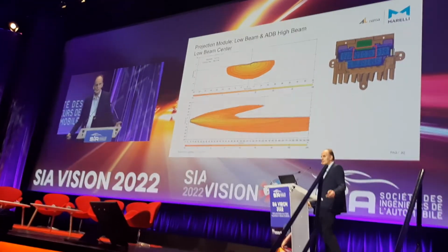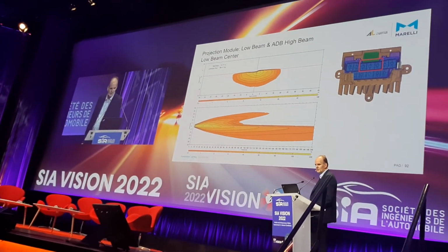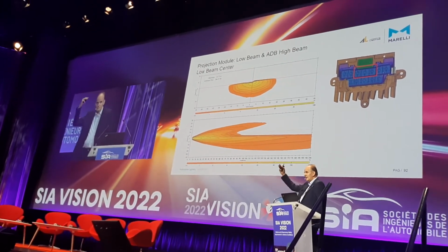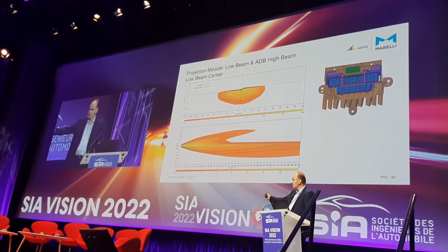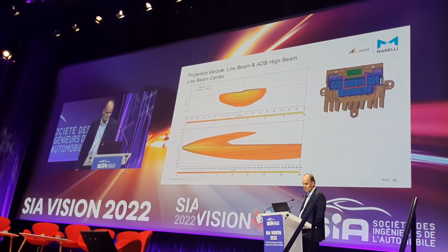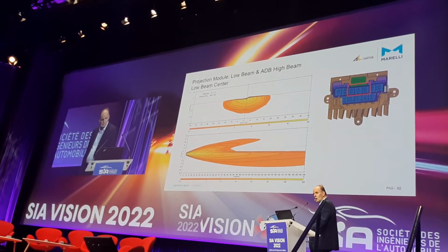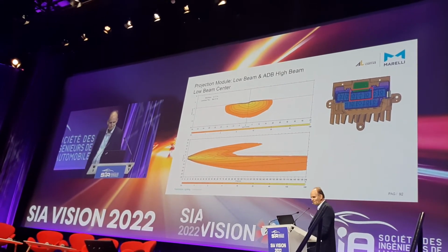If only 1 candela per square meter is okay for the driver, and the street illumination already provides 3 candela per square meter, it doesn't make sense to put 40 watt onto the road. 10 watt could also be okay per headlamp.